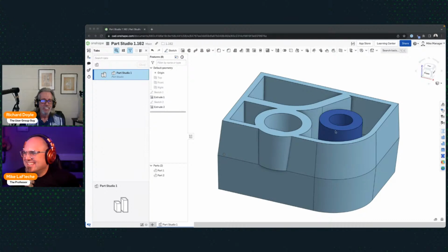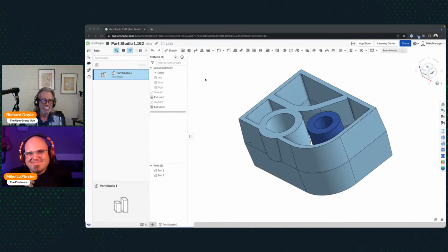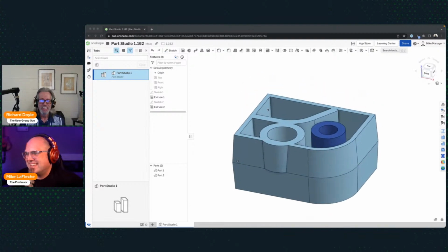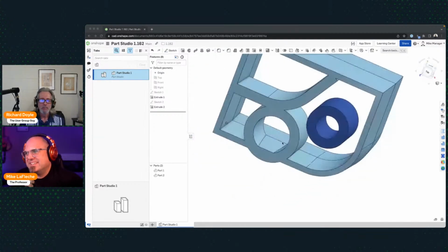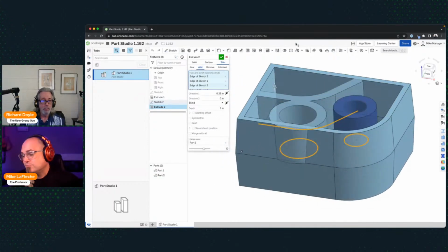So let's keep it going. But as you can see, we're just getting started here. Well, wait till they see the other stuff. I know. And this was the basic stuff first, which I like to get out of the way. But thin extrude just works really nice. You can use it in very complex rib situations. If you're designing bracketry, any kind of thin plastic parts with a consistent wall thickness, there's many reasons to do a thin extrude. Tubing with only one circle in your sketch. There you go. You get tube. Oh my gosh, I didn't think of that one, Richard.